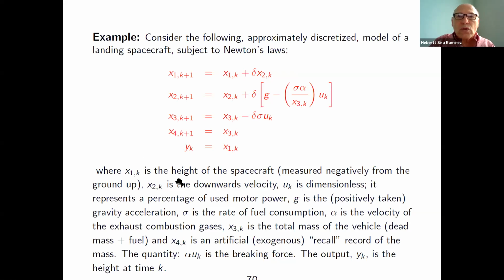And the other issue that emerged right from there is the existence of some dynamics which is complementary to the input-output dynamics. This dynamics is known as the remaining dynamics or the hidden dynamics or the zero dynamics. And the stability of that dynamics was crucial for the success of the control scheme that we try to design on the input-output relation being now a simple linear structure.